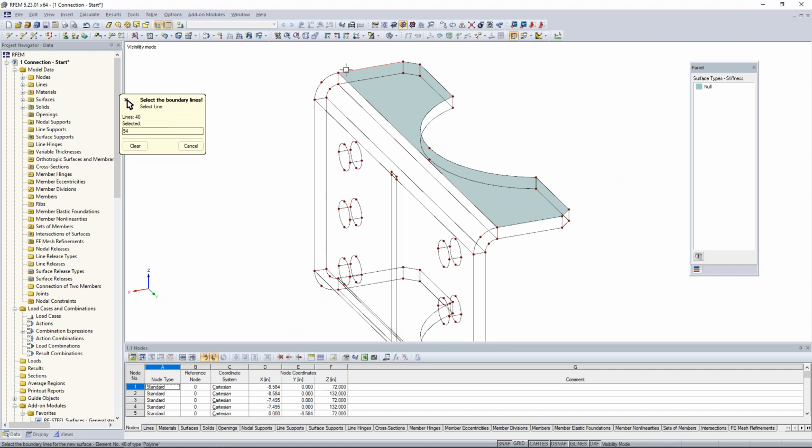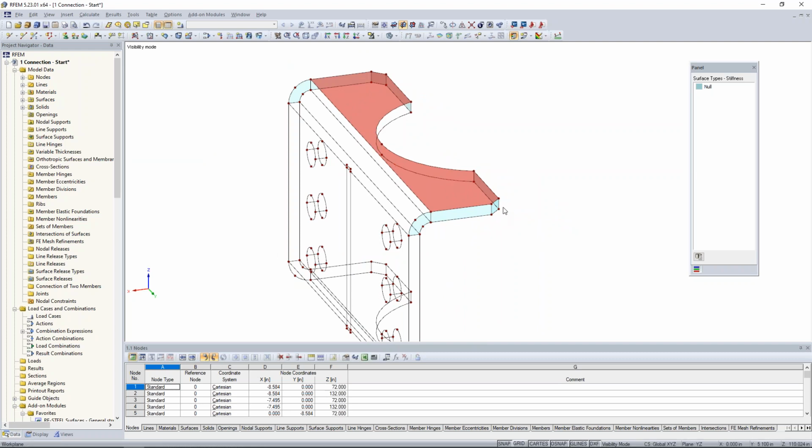Now, the exact same thing needs to be done for all of these smaller surfaces around the edge. So I'm just going to, again, move around in the circular direction. I'm going to skip this curved surface, and we know the reason why, because this is not in a single plane. So my element that I am utilizing right now only allows me to define these surfaces in a single plane. And we'll actually utilize these curved surfaces here on the side because these are in a single plane still, and we are done.